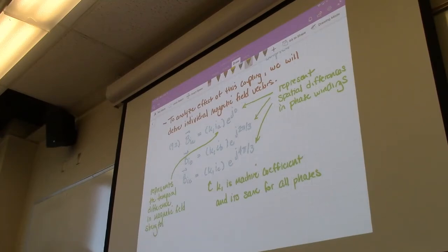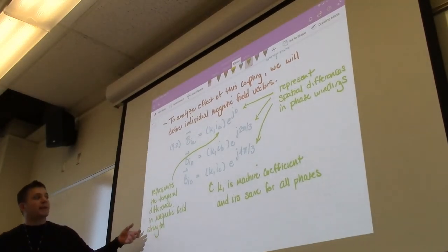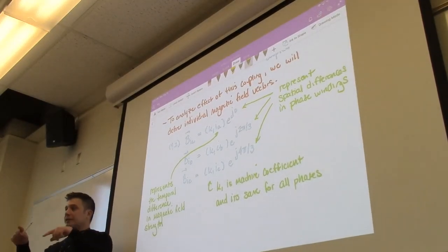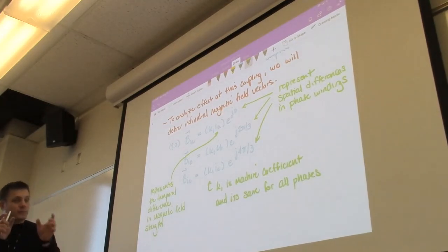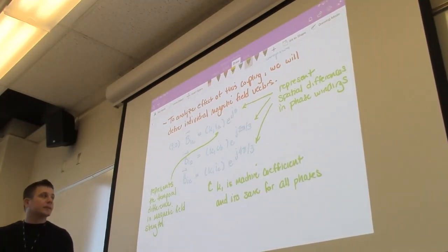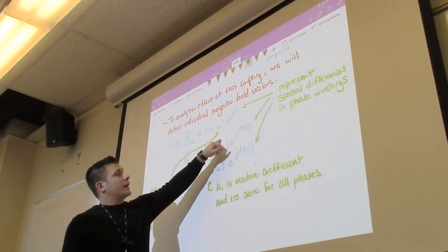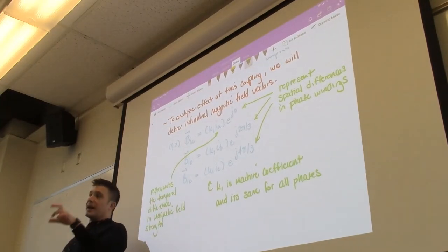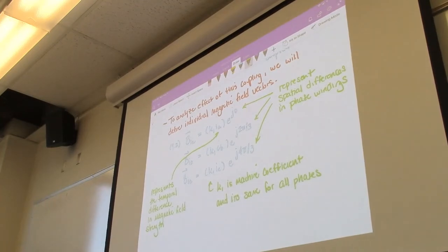And then in IA, IB, and IC, although we haven't included that mathematically yet, that's where we'll have the temporal difference in the magnetic field strength, right? Because IA, IB, and IC will all be separated by a certain distance temporally. What we can do later on, which will be the next step, is include that temporal difference and put everything in terms of IA with a rotation associated with it.